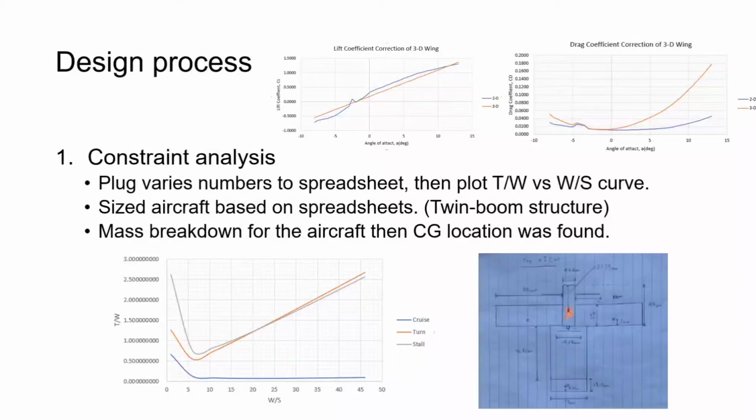After that, we put some numbers in our other spreadsheet too, using NACA 2412 as the airfoil. We found that our 3D wing lift and drag were quite ideal. We also tried putting an H-boom design in our UAV, which our spreadsheet showed to be successful, and the H-boom UAV has multiple advantages regarding structural and storage problems.